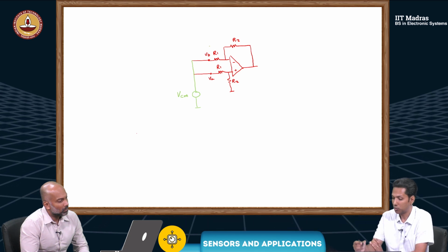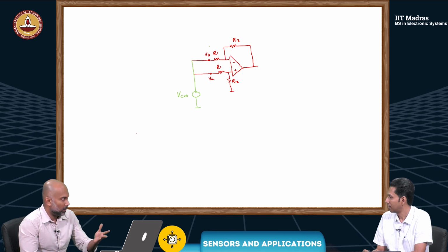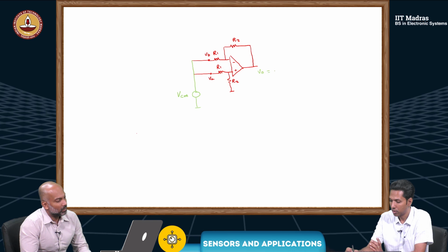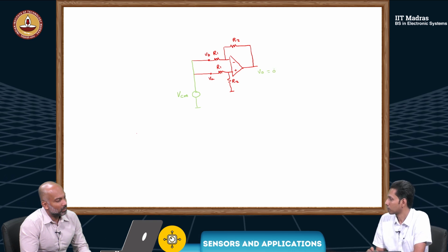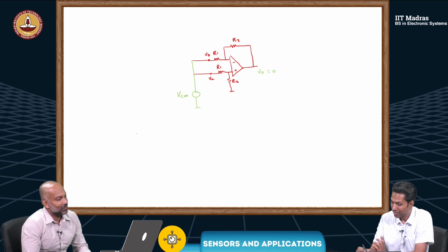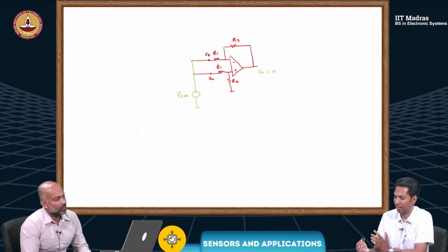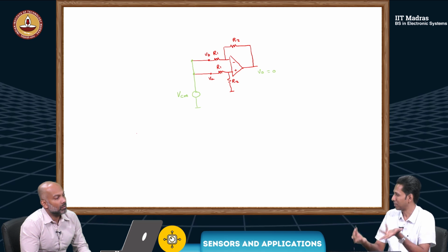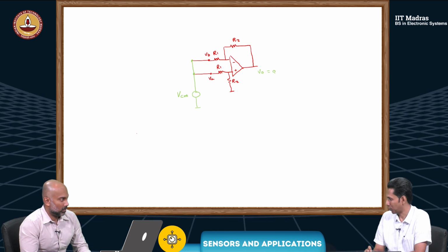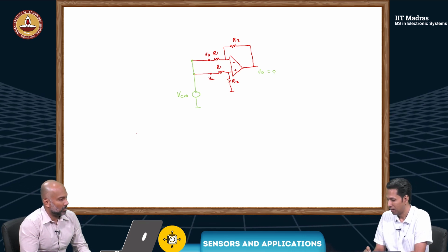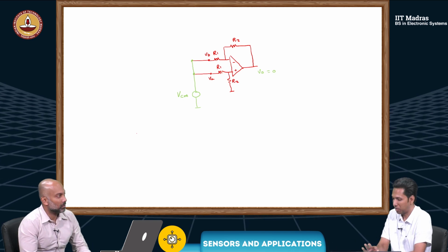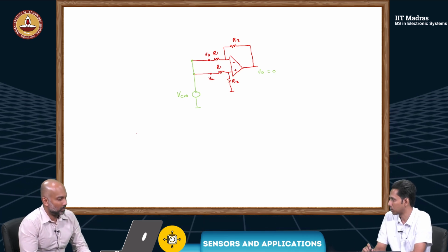It was VA minus VB in this amplifier, so the output voltage will be 0, since we're giving the same voltage. But these two terminals can be at some voltage. It can be both at 2 volts, but your output voltage is 0, theoretically. If there is some mismatch in these resistors, it will not be valid. But if you have matched resistors, this is possible.